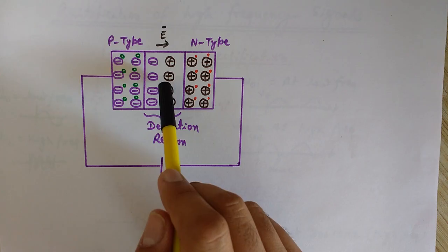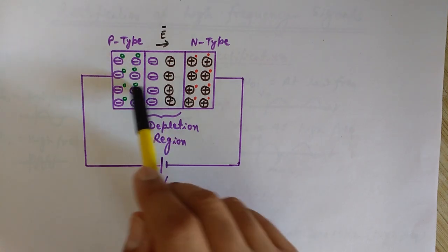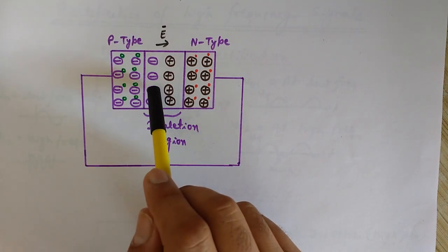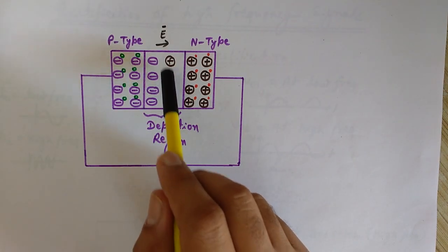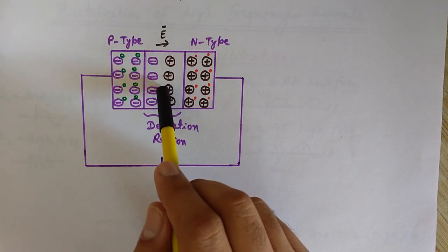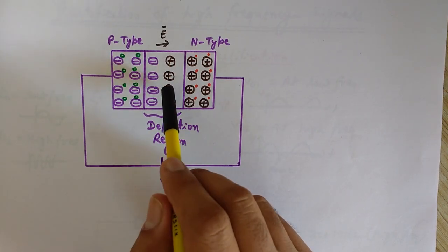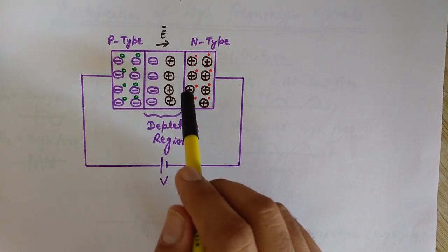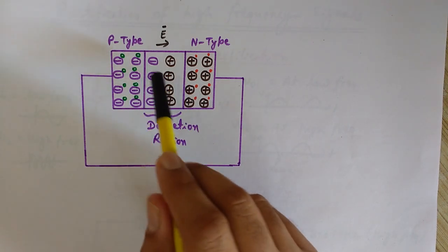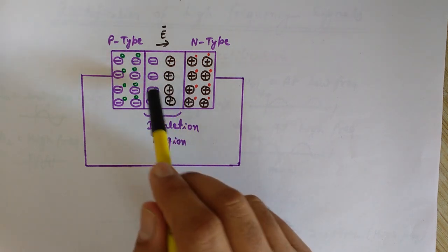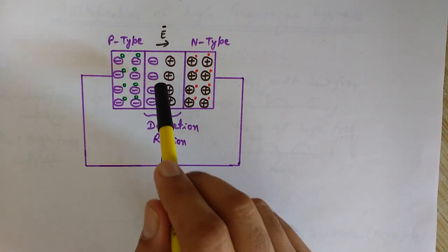The time that it takes to remove these charges from the depletion region is known as the reverse recovery time. So it causes some delay. Therefore, normal diodes cannot work at high frequencies, because at high frequency input signals the direction of current changes very fast, so the charge remains stored at the depletion region.